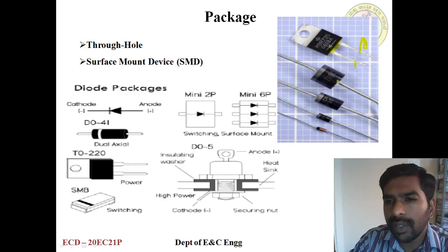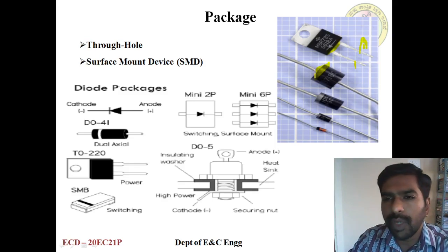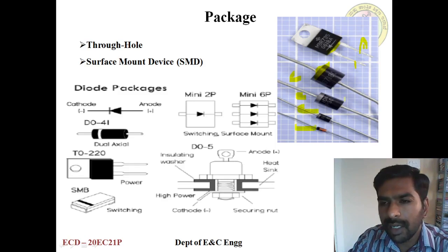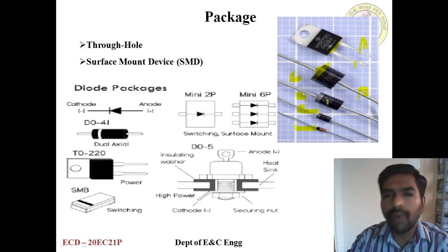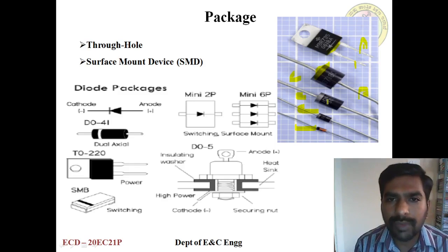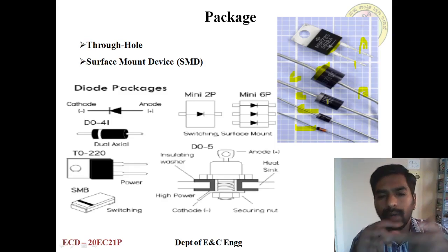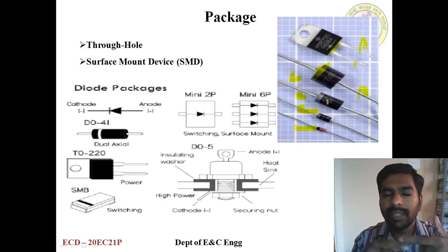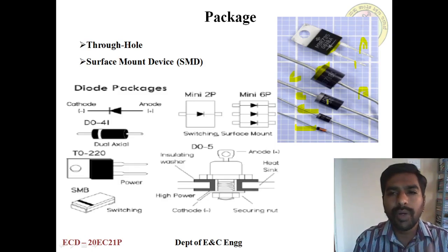And these are the diodes where you can have one white colored band across one terminal. This indicates that it's the cathode. And the other terminal is the anode. See how we identify the terminals of the diode: the one with a color band, white color band or silver color band, is the cathode terminal. The other point will be the anode.